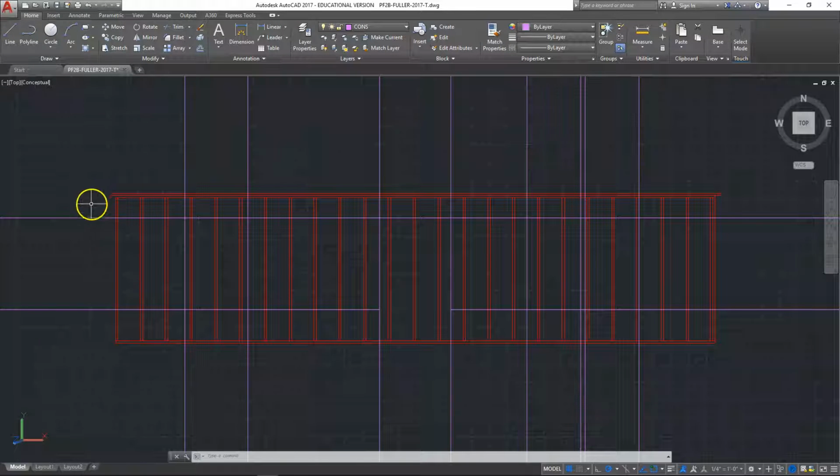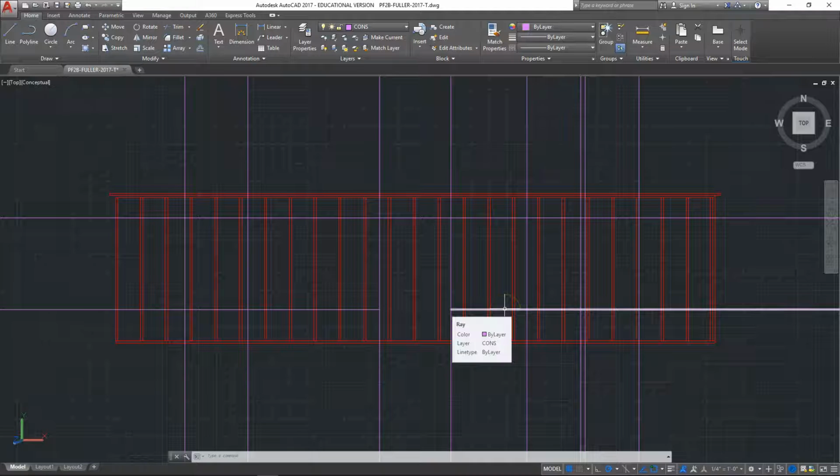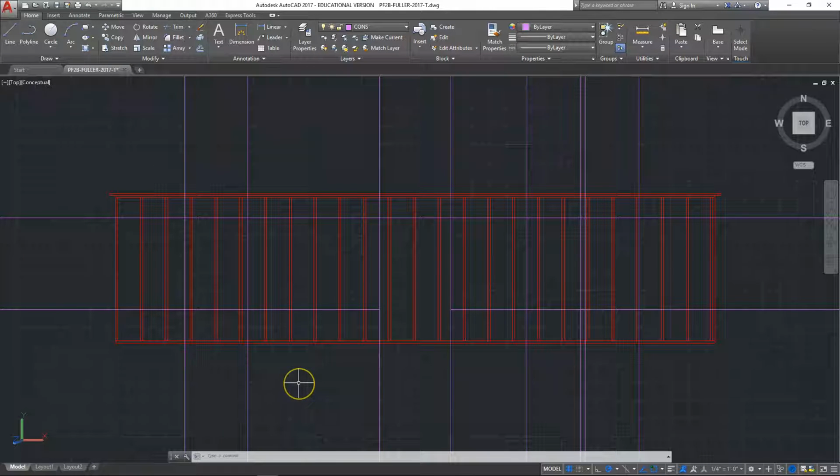Place another line closer to the bottom to mark the sill height of the windows. On this drawing, the windows are placed at 20 inches from the top of the foundation to top of the windowsill. Remember that the maximum for bedroom windows is 24 inches from the top of the foundation. I went ahead and cut the portion of the construction line across the bottom of the doorway because the door goes all the way down to the foundation.